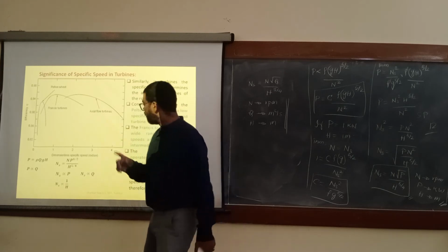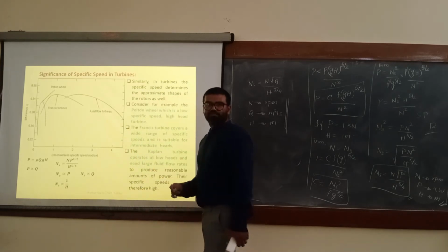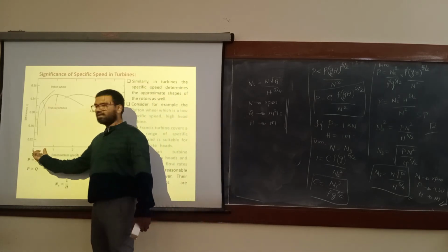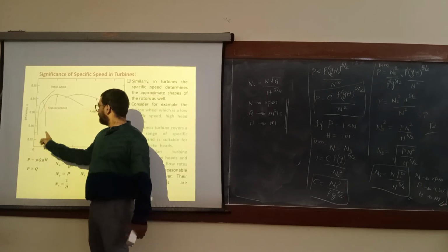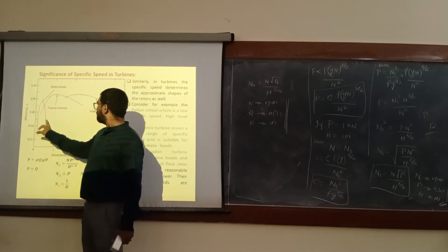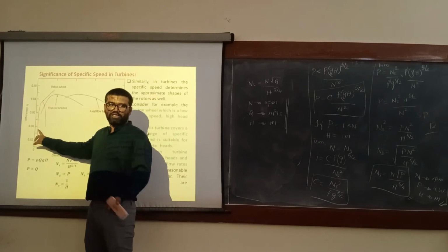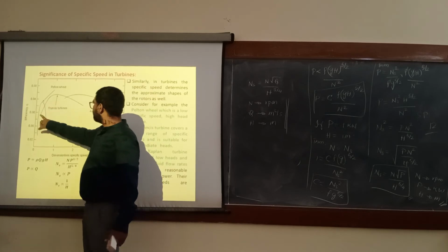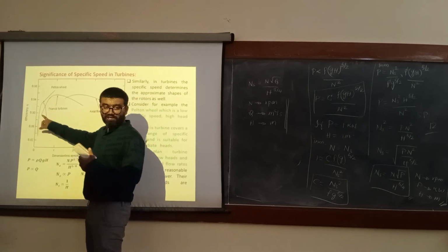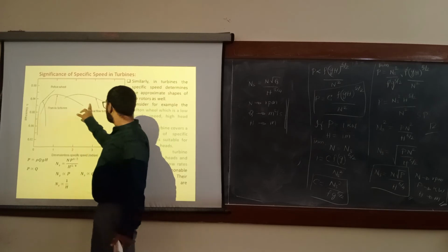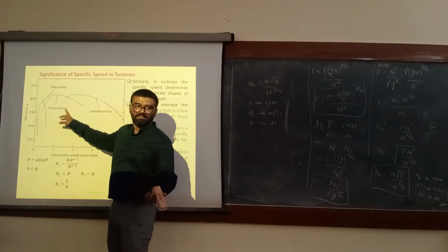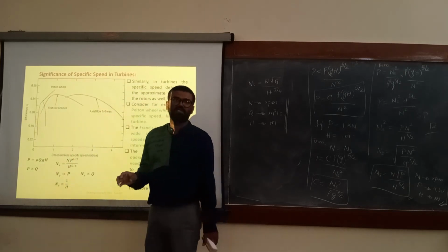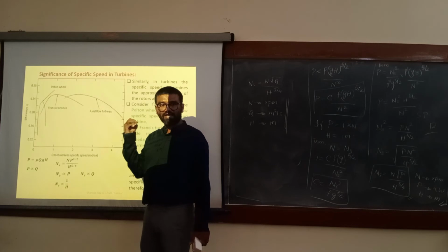For Jog Falls, if you use the Pelton wheel, it produces more power because the site condition has a low specific speed. If the specific speed is low, the Pelton wheel works effectively and produces more power. The Francis turbine has lower efficiency under this condition, and the Kaplan turbine may not work there. So if you use the Pelton wheel, it produces more power at higher efficiency.